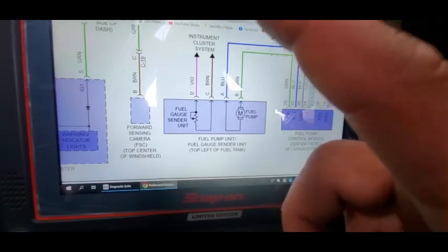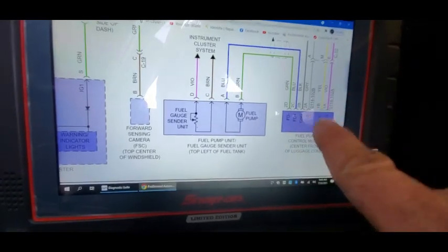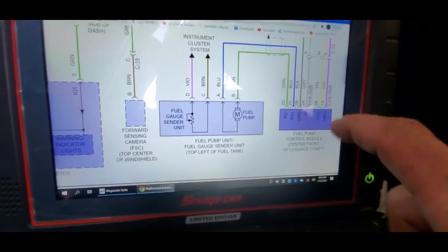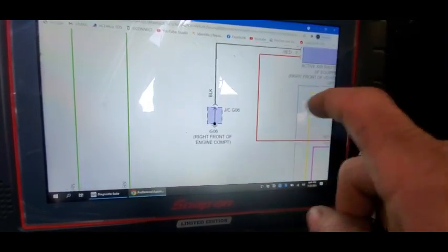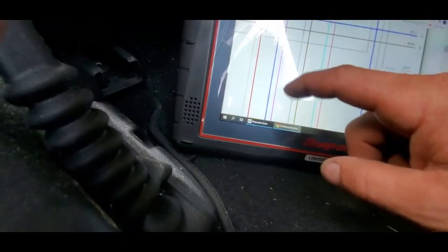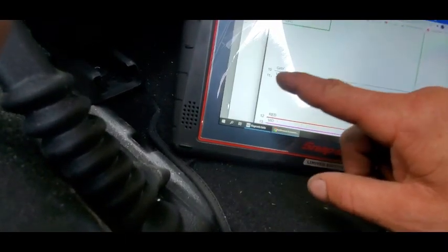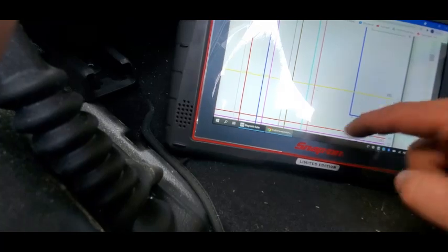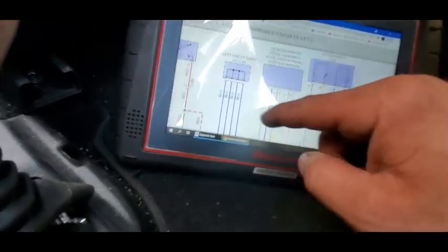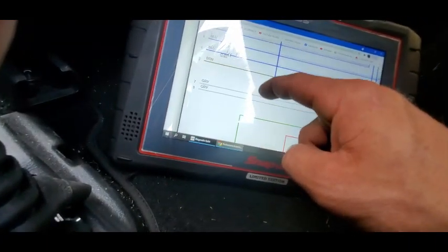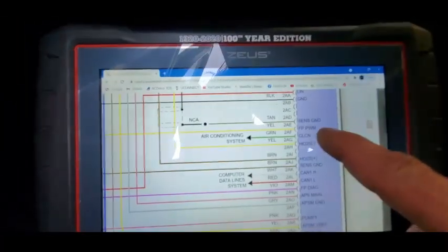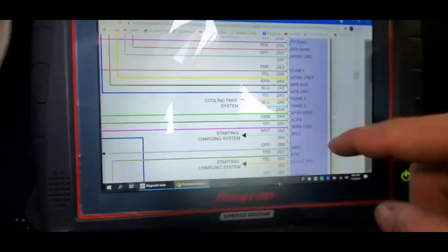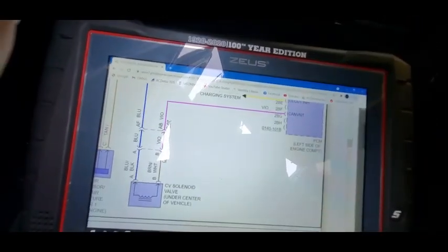Now, when we were cranking it, the duty command, this fuel pump command, FPC here, this yellow wire, if we follow that, yellow to 11, next diagram. Same thing with that diag wire, 11 yellow to 9, next diagram. Going quick here, guys. 9, you can see right here, fuel pump pulse width modulation, right from none other than our PCM, okay?